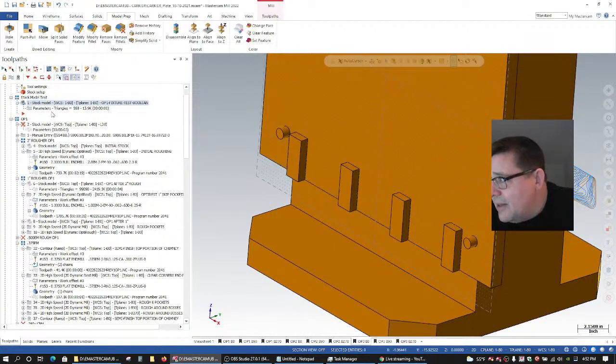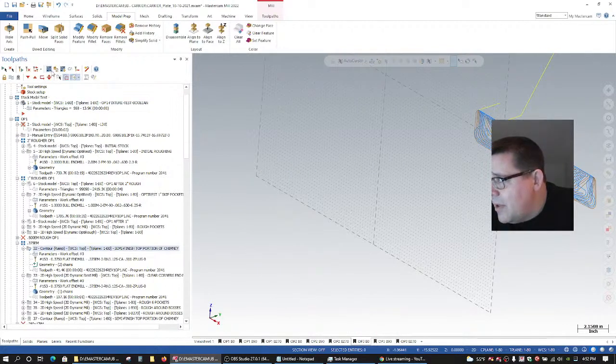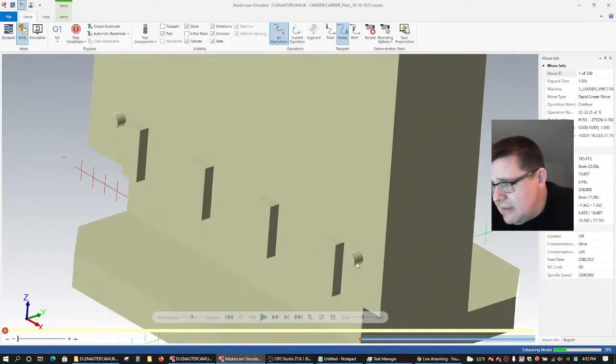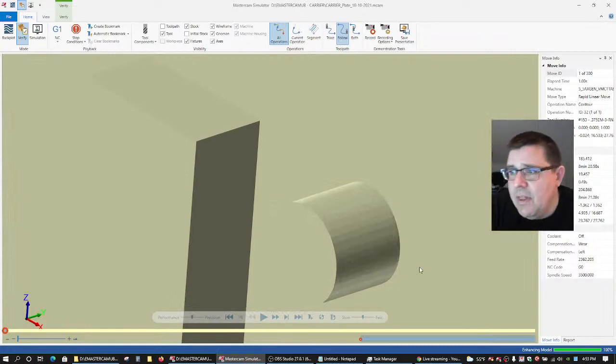And if I go back into verify, contour ramp, we go back to verify. So that's a 1 thou stock tolerance. So you can see manipulating that tolerance whenever you have a round object, it is important. The tolerance value you use will affect the accuracy of the models you're bringing into verify.